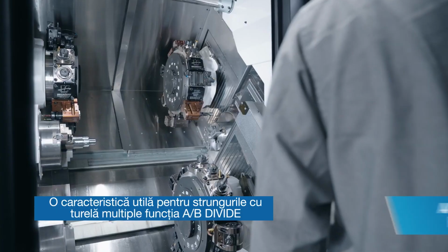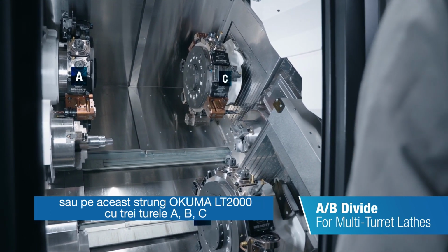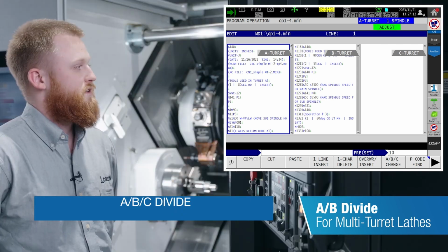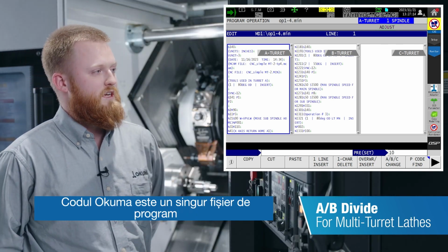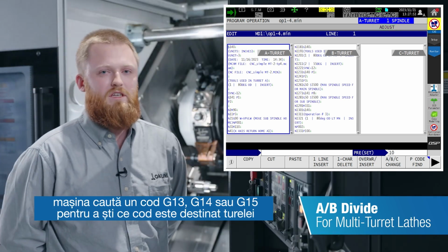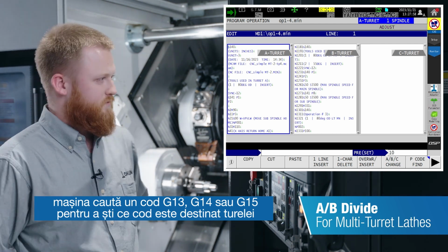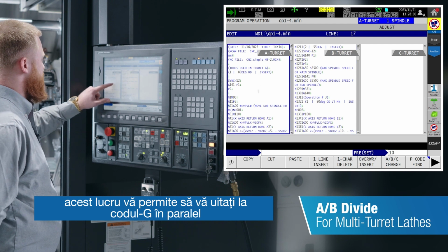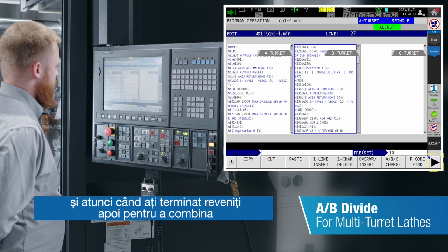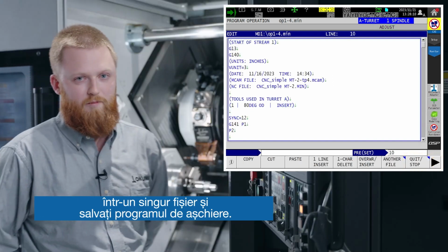A handy feature on multiple turret lathes is going to be our AB divide, or on this machine, the LT2000 with the C turret, ABC divide. OKUMA code is all one program file. The machine is looking for a G13, 14, or 313 to know which code goes for which turret. This allows you to look at the codes side by side, make sure all your sync codes are where they need to be, and then when you are done, you can go back to combine, put it in one file, and save your cutting program.